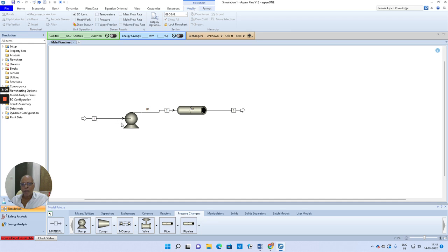So essentially for the pump, you need to calculate the rating of the pump, the capacity of the pump, the power required by the pump in order to force water across this pipeline, which is having a length of about 4500 feet and over a height of about 3000 feet. So whatever may be the pressure drop in this entire pipeline across the fittings, you should be able to increase the pressure of water by using this pump, so that water will be able to come out from the exit of this pipe at 3000 feet height.